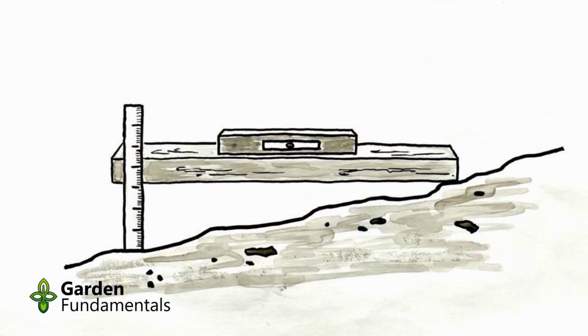So how do you measure slope? Well, here's a pretty simple way. You need 3 things. You need a ruler, you need a level, and you need some sort of board, preferably one that's straight. So in this picture, I have a 2x4 that's say 8 feet long. I put the level on top of it, and I take one end of the board and I lay it on the ground. Then I take the other end of the board and lift and lower it until it's level. I then measure the distance between the board and the ground.